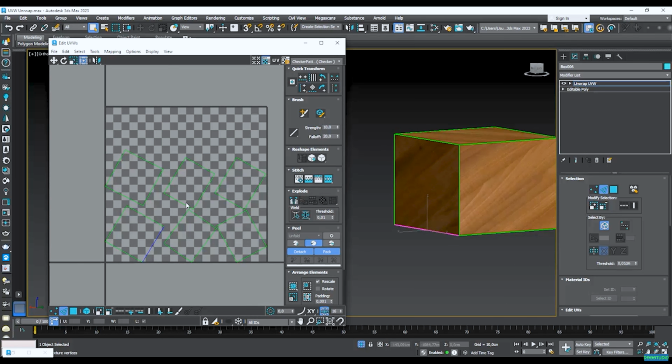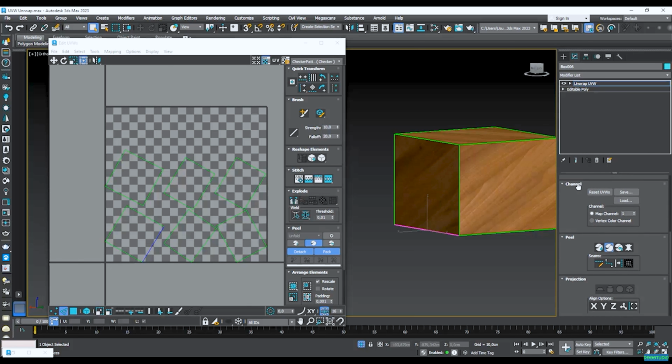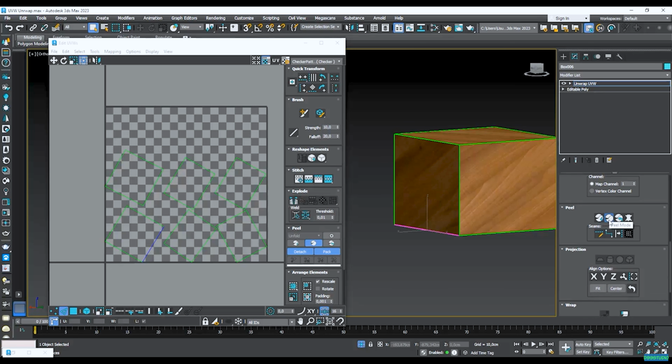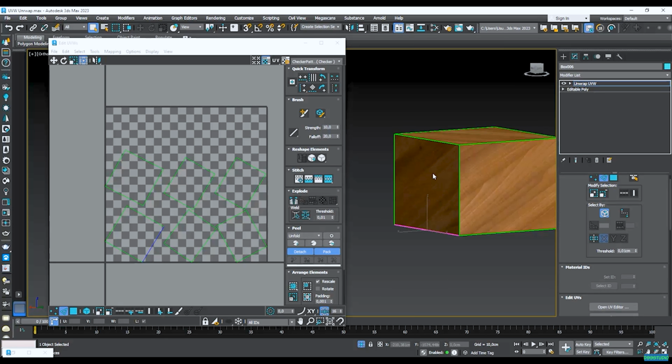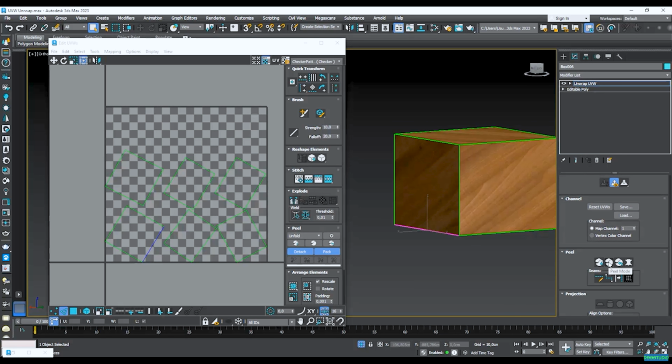and there I've cut all of my edges and ended up with 6 faces. Now what I need to do is just to align them again. So make sure that you have your snaps off. I'm going to align them with my edge selection. But before that, let's go down here and unselect my peeling mode so that we no longer use the edges to peel anything else. We've done cutting edges. Don't forget to disable your peeling mode.